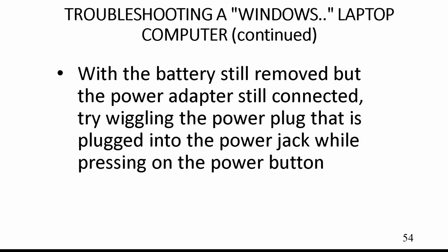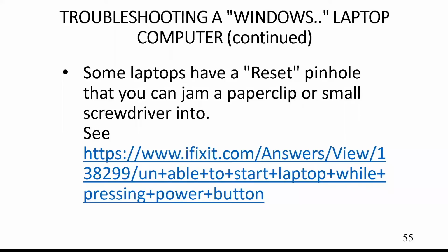If the battery is still removed and you attach the power adapter, try wiggling the power plug where it's plugged into the power jack of the laptop. Some of those plugs, especially on the lower end laptops, go out. And when you wiggle it, you can get them working. So my quick fix is to put a piece of tape there and push it against one side or the other, and the guy has a working laptop for another year or two. Now, if I was really going to fix it for him, I'd try to replace the jack, but that's beside the point, right? These are quick fixes to get you up and running that don't cost anything.